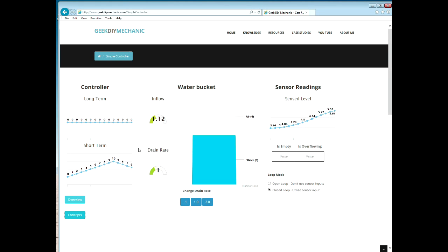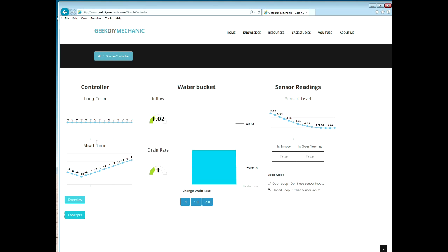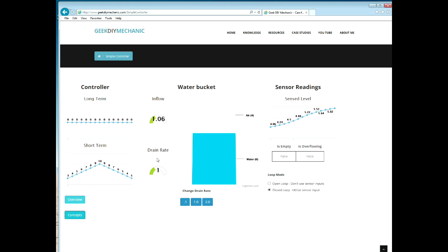The thing to understand is long-term and short-term. In regards to a car, those have to do with long-term fuel trim and short-term fuel trim. Those two help you diagnose many issues in the car. Again, if you see either one of them way out of whack in a car, it's plus or minus 10%. In other words, if they're in the plus or minus 10% range, that's okay. If it's outside of that, it's showing you there's an error.